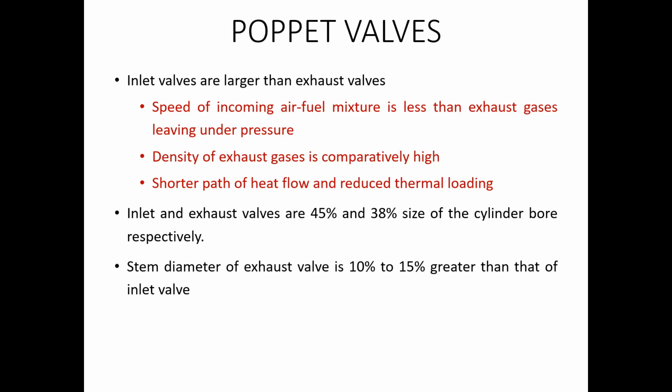Now there are certain interesting things which you may not have noticed. Usually the inlet valves are found to be larger in size than the exhaust valves, or the exhaust valves are made smaller than the inlet valves. There are certain reasons. First, in inlet valves, the speed of the incoming air fuel mixture is less than that of the exhaust gas leaving under pressure.